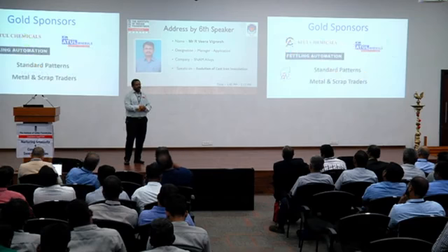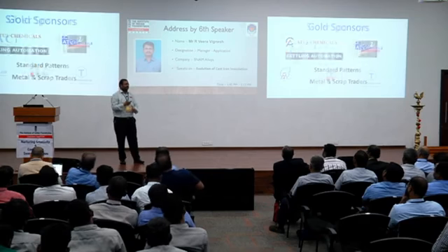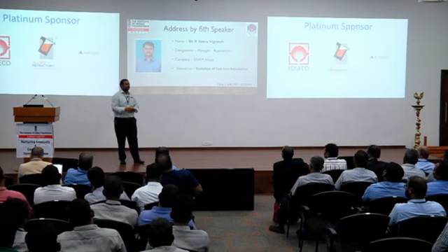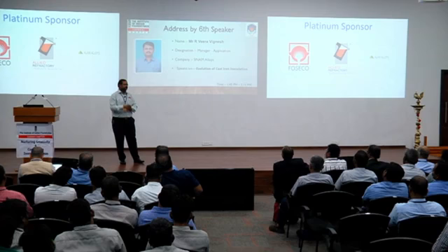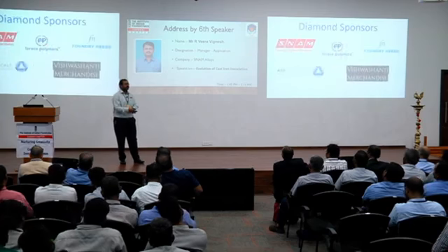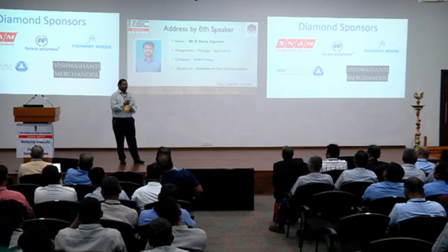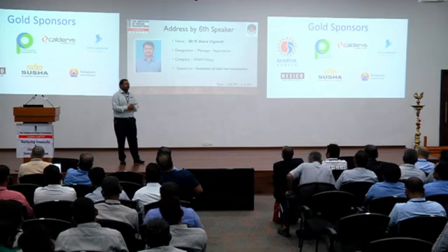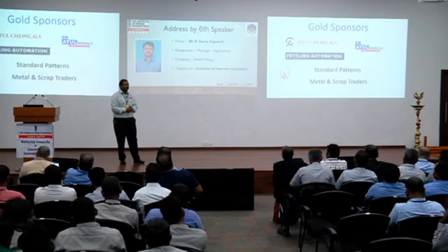So what we can ensure in our liquid metal or even our solidification is we can avoid forming network of carbides of all these elements. So it is not just molybdenum carbide that gives you failure. It is network of molybdenum carbides which is giving you failure. So if we understand why networking of molybdenum carbides happens, it is the cooling rate of casting that decides how the molybdenum carbide forms in the liquid.